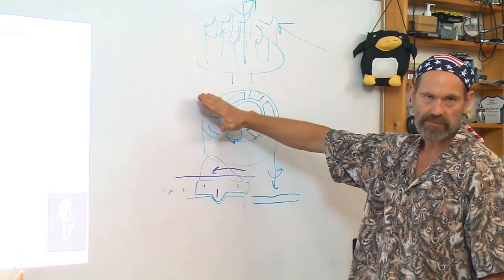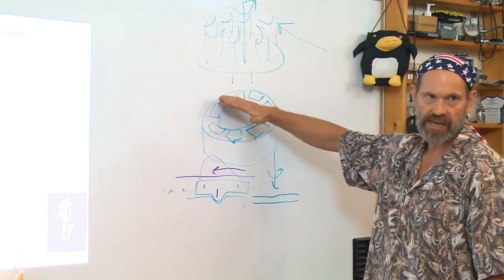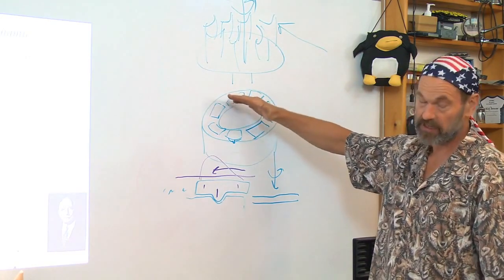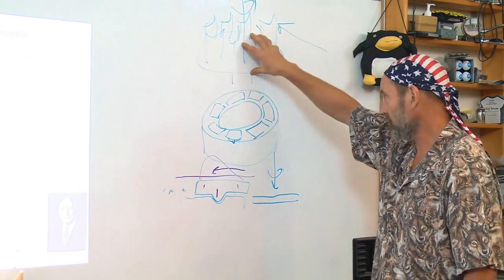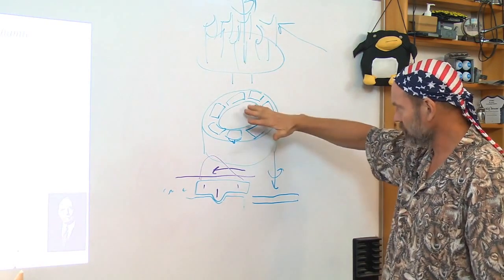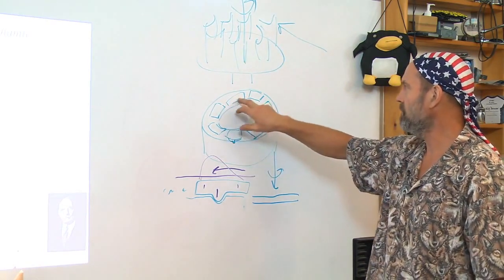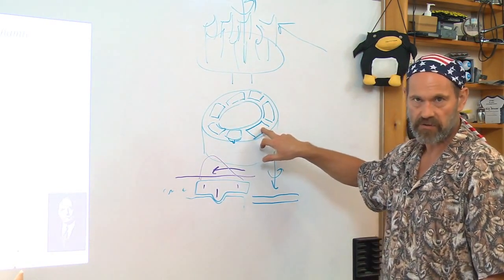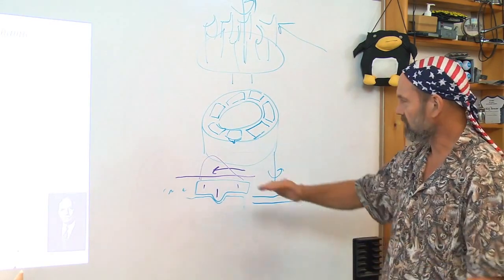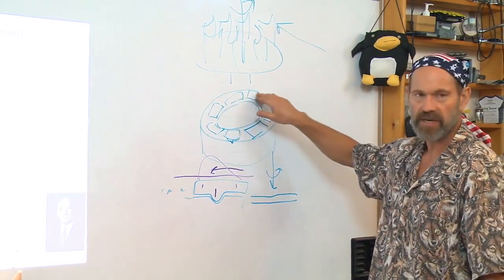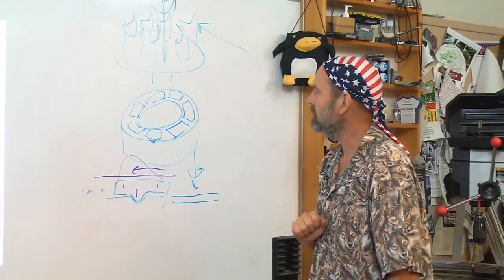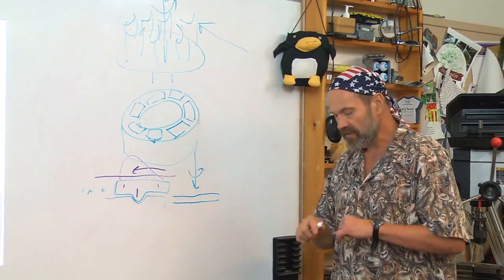on their entire top surface when there is just a static load and no lubrication. Put the turbine impeller down here, push, and it should touch all of them. And remember we talked earlier about rubbing a bearing, so that's how you could tell that they're all at the same height, by rubbing a bearing and scraping them as appropriate. So this brilliant invention,